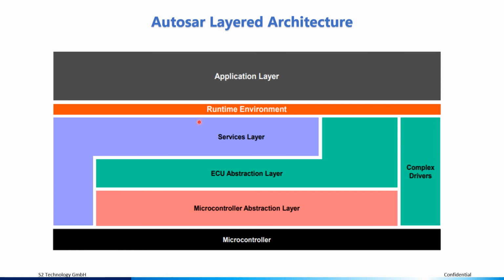And the complex device driver is a module which implements non-standardized functionality within the basic software layer. So these non-standardized functionalities, like injection control or electronic valve controls, can be wrapped up and put into the AUTOSAR layer so that they can communicate through the microcontroller directly to the application or via the RTE.